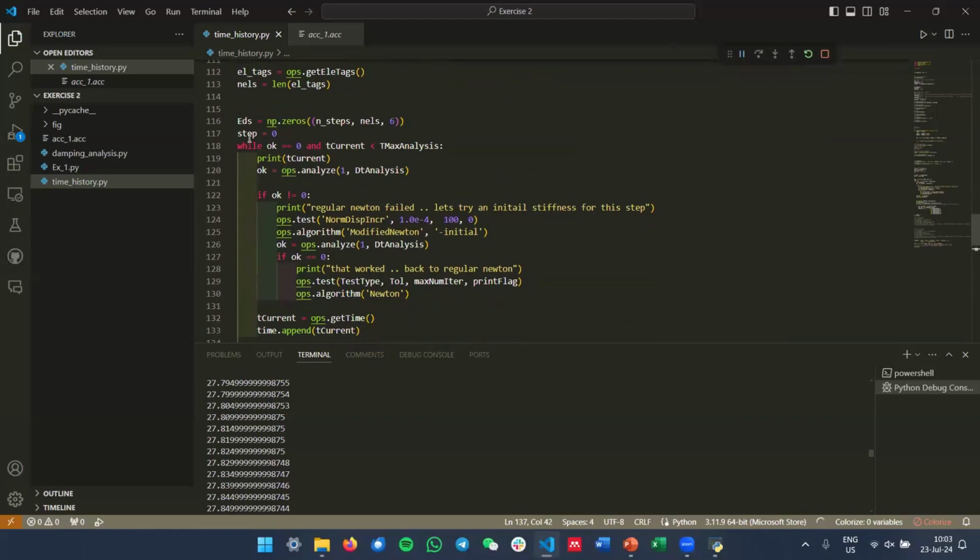Here, I'm using this approach since the problem is elastic, so you don't have problems. But with nonlinear analysis, you can have convergence problems in the evaluation of the structural stiffness. When you pass from element stiffness to section stiffness, the stiffness of fibers, for example, and then go back to evaluate the stiffness of the structure, you can have problems there.